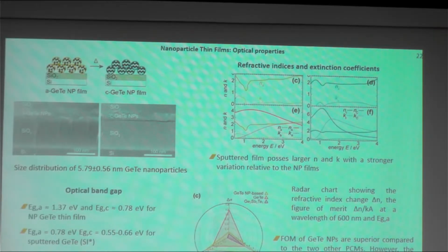On the previous slide, we showed another, reverse effect, where the crystalline nanoparticles had a larger Eg than the amorphous. And here we also see an increase in the band gap for the nanoparticle thin film for amorphous. Here, this is a real thin film. It shows 0.8 eV, and crystalline here 0.6. Here, this is also a difference of up to 0.2 eV.